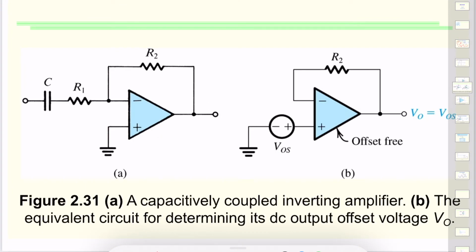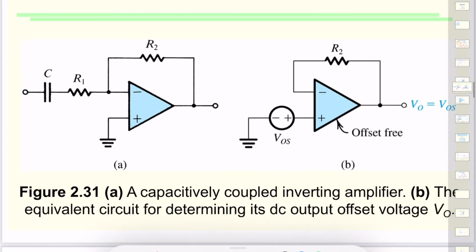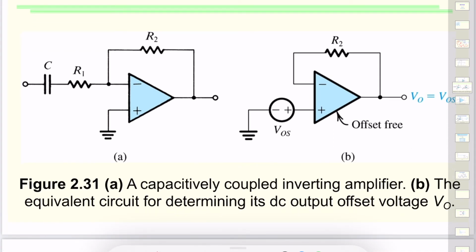Another solution to take care of this imperfection is to use capacitor coupling for the op-amp. This would result in zero gain for DC, but your output would be equal to the signal that's fed to the circuit. In this case, the capacitor forms an STC, a single time constant circuit, with R1, and this would be a high pass filter with an omega that we can calculate from that capacitance.